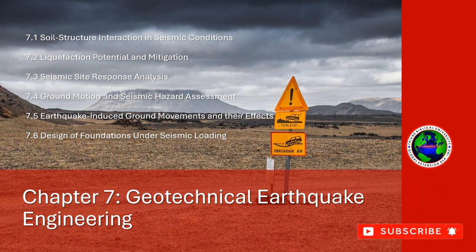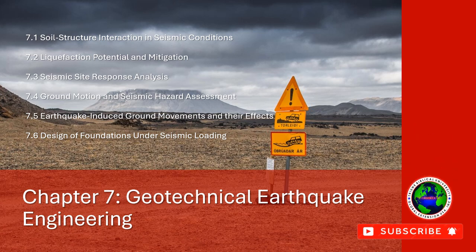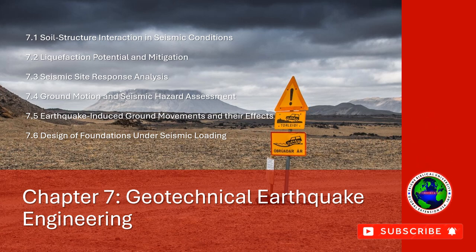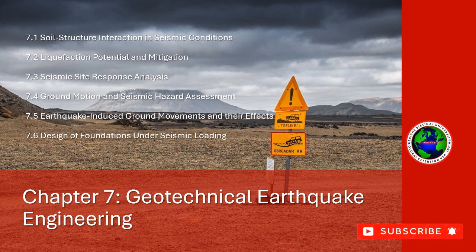1. Site-specific ground motion analysis. Conducting seismic site response analysis helps in determining the expected ground shaking at a particular location. This analysis considers local soil properties, bedrock conditions, and seismic wave characteristics. Site response analysis is essential in identifying areas where amplification or settlement is likely to occur.